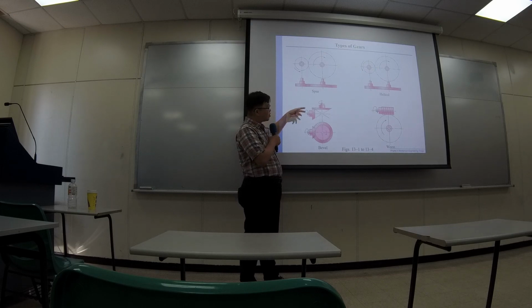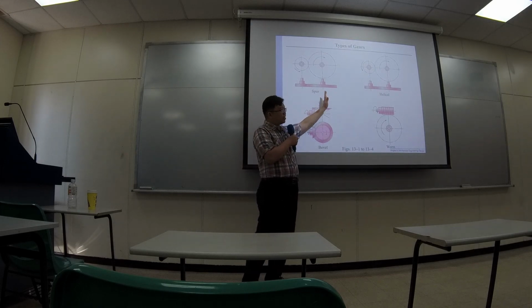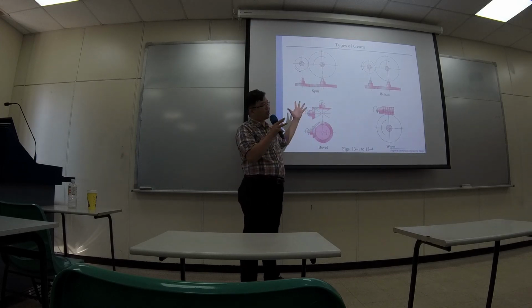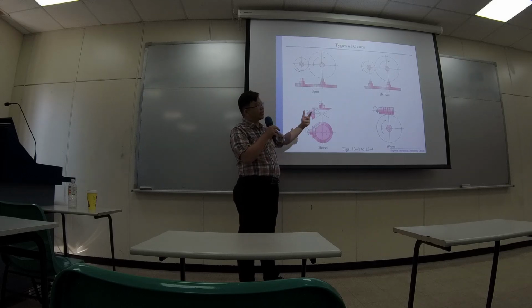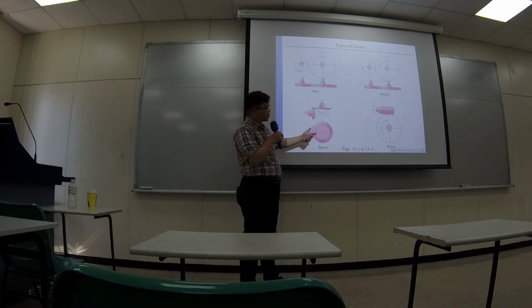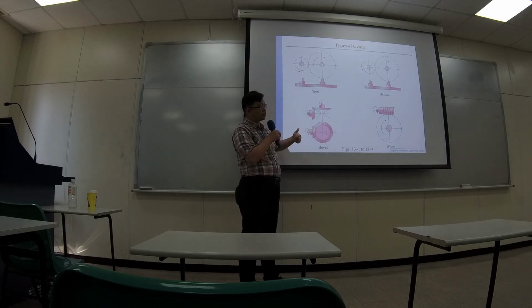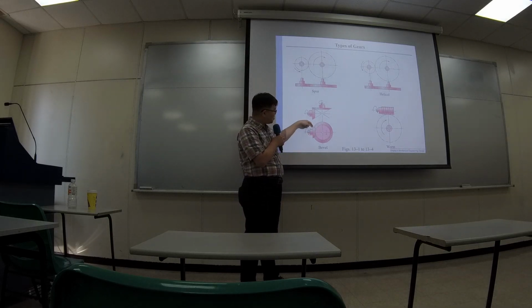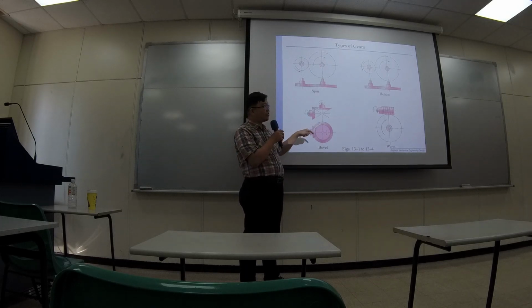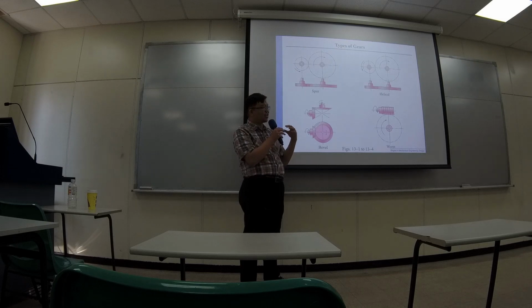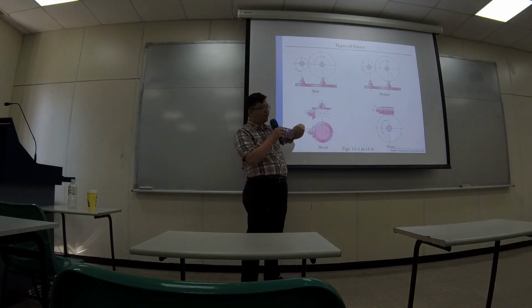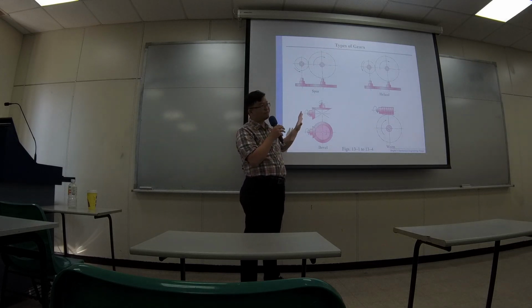And sometimes when the driven one is carrying different kinds of loads, maybe there is a reaction force applied to a certain direction, so it's not good for the teeth. So sometimes they want to generate helical shape of the teeth so that the teeth can carry forces from different directions. Okay?